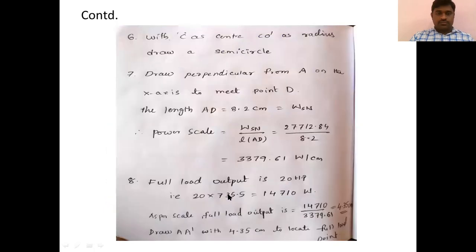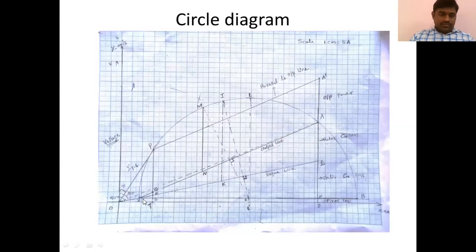Now if you see the figure, with respect to the voltage axis, this phi naught is 78.46. With the no load current of 1.8 centimeters I am placing on this line. So here 1.8. From here I have drawn a horizontal line like this, which is parallel to your x-axis. So this O dash B line you have to draw.